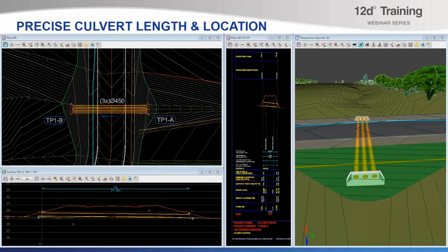Today's webinar will demonstrate how to align and grade a drainage string culvert with precision in both the horizontal and vertical to best suit the batter slope of the road it crosses and to allow for an integer number of prefabricated pipe and box lengths. Plan and long section plots of the culvert will be produced, and the culvert and its head walls will also be converted to trimeshes for use beyond hydraulic modelling, for example in road design and BIM.